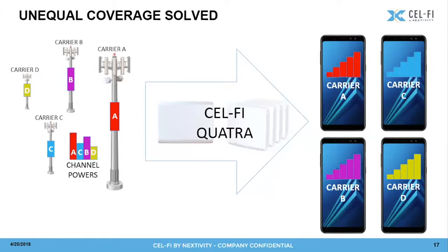Okay, one more question while we're here. Rick wants to know how much isolation in dB is between the adjacent channels. For example, if you set up a Quatra solution next to an AT&T base station emitting 740 megahertz, how much leakage is there onto the Verizon 751 meg? So the phase noise, the skirts out of base stations are fairly good because they use good cavity filters.